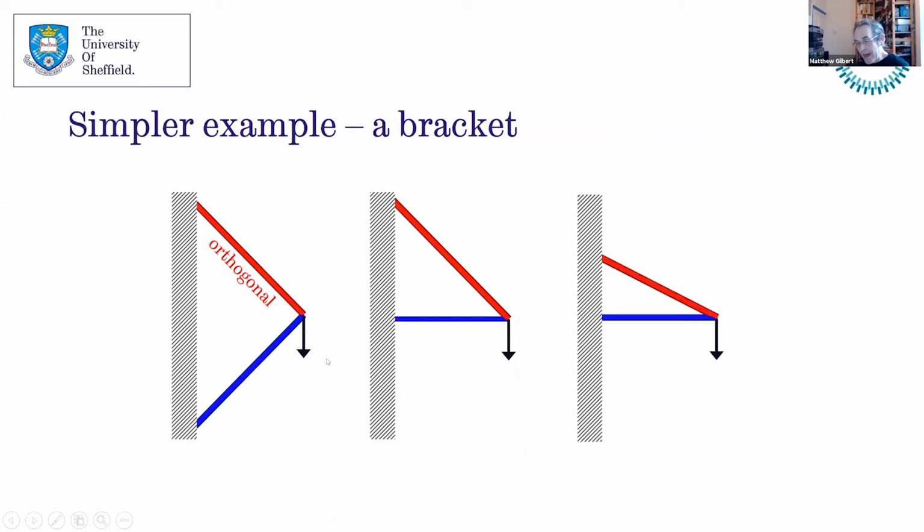And if we compare the volume of the structure on the left with the structure shown to the right, we can see that we save significant amounts of material. So the structure on the right, for example, requires more than double the volume of material than the structure on the left. And that's got a subtended angle, I think, of 22.5 degrees, then 45 degrees, then 90 degrees.